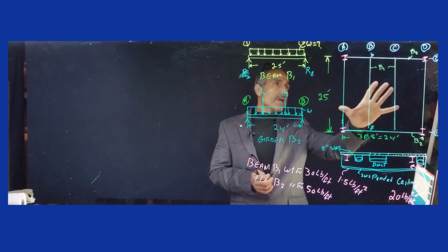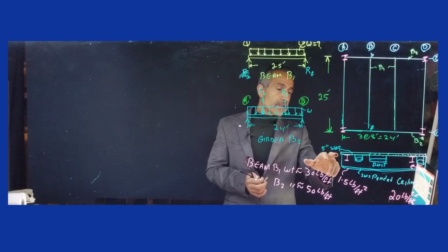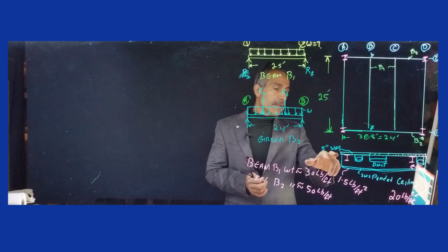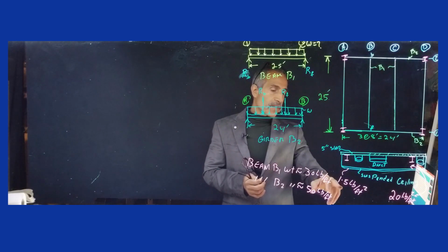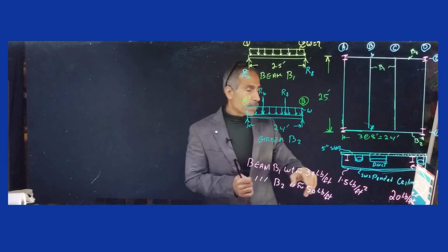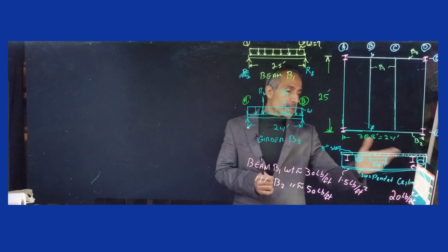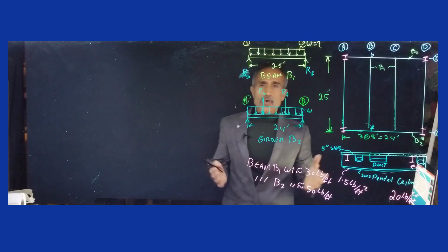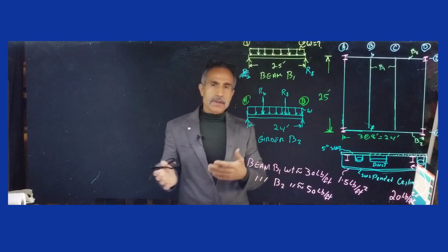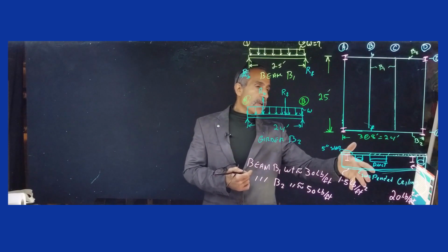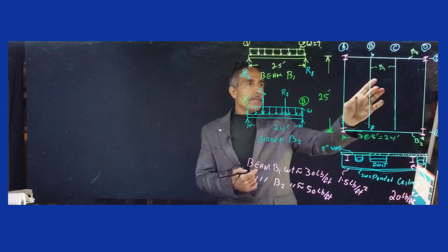When we take a cross section here, we're going to see the concrete slab is about 5 inches on top of the beam, and then you have the ceiling and all the other stuff. The ceiling itself is 1.5 pounds per square foot. And watch your units. Then all the stuff inside here, the ducting and all the pipe, let's say comes out to 20 pounds per square foot. You usually find these in a code, and they tell you what to use. And based on experience, a lot of designers can tell you all that stuff. So now we have this. Our goal is to find out how much load is on this beam B1.